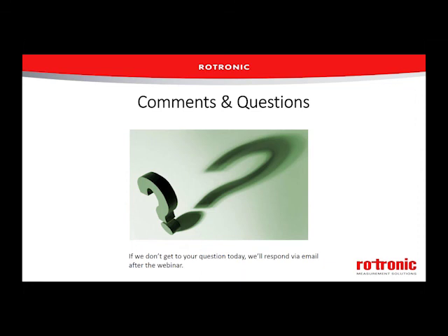Okay, well, within the uncertainty budget, essentially what you need to do there is find a good humidity calculator, and there is one available on the Rotronic website. In there, you can calculate out what the temperature sensitivity value is. It changes for every humidity, and even over temperatures it will potentially change slightly. So it's something that you need to calculate out for each test point that you've got. It's not something that a manufacturer would specify because it's not instrument specific. It's actually going back to the fundamentals of humidity and understanding relative humidity and how temperature affects it.